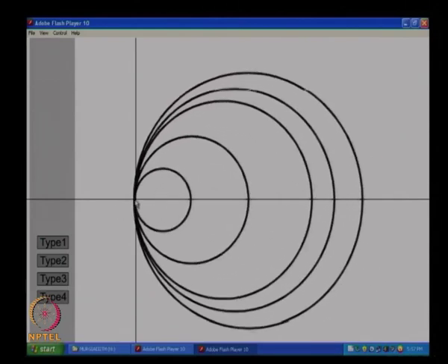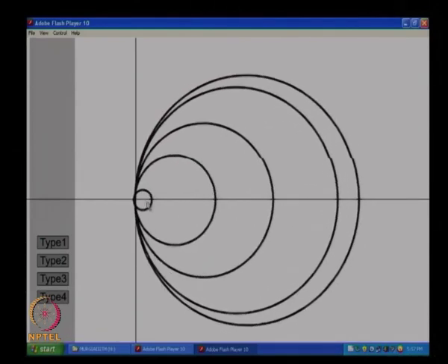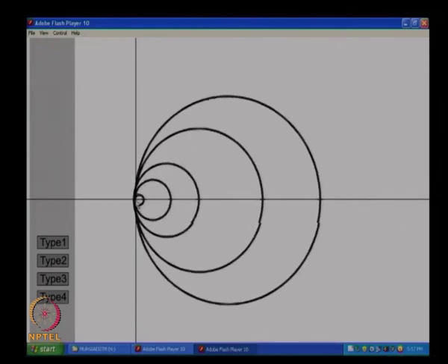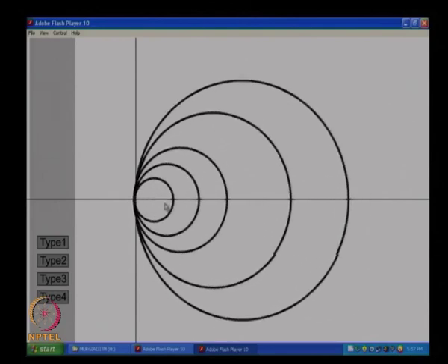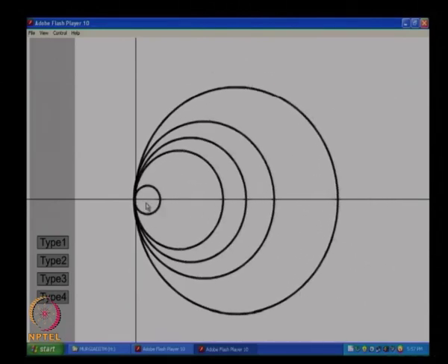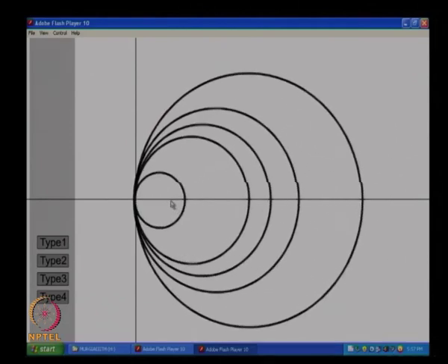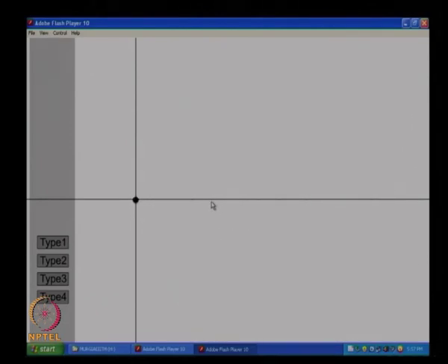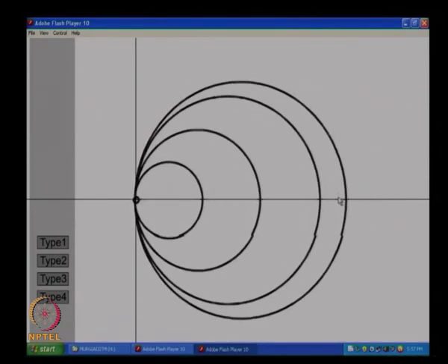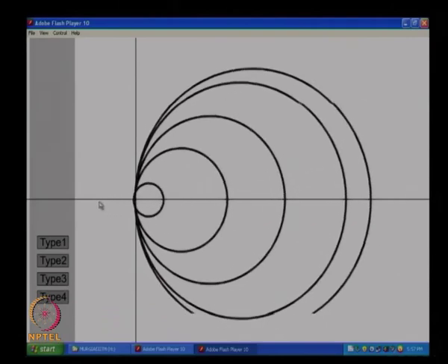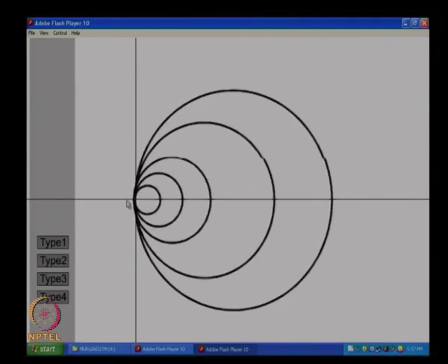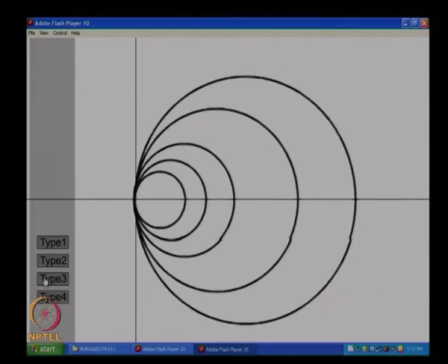It is like running in a train, if you think about it. The train is going this way and you are running inside the train in the direction of the train. For a person standing outside, you will see the velocity of the gas plus the velocity of the wave running on it, both together. So we get u plus a as the speed of the wave here. On this side it will be u minus a, actually you can call it u minus a in this direction, and you will find that that is 0 in this special case.